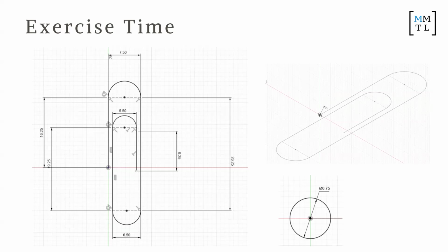So the circle that we're referring to here, if you take a look at your paperclip, is the cross section of the actual paperclip. Make sure you start both your sketches on the origin point, or else if it doesn't intersect, the computer can't sweep it. You can go to semi-circle, or you make a circle and then just delete the other two.